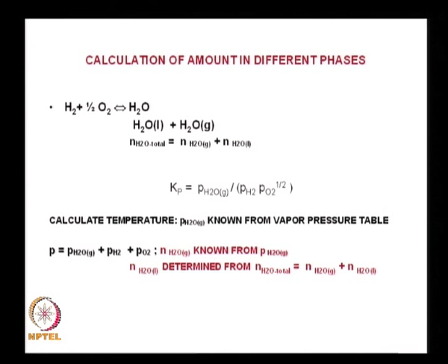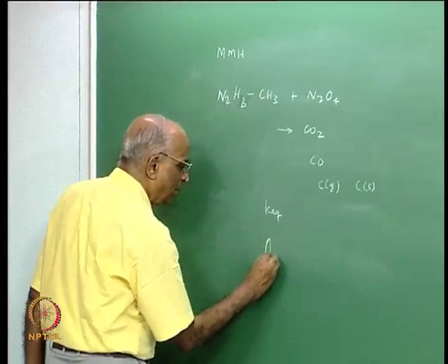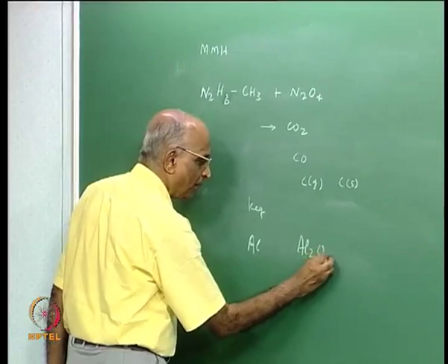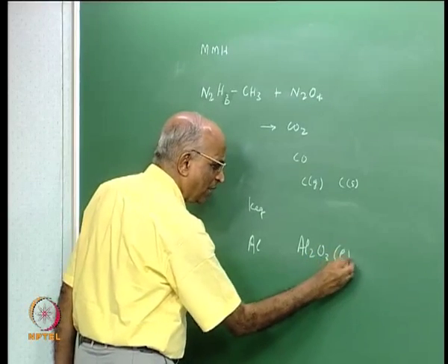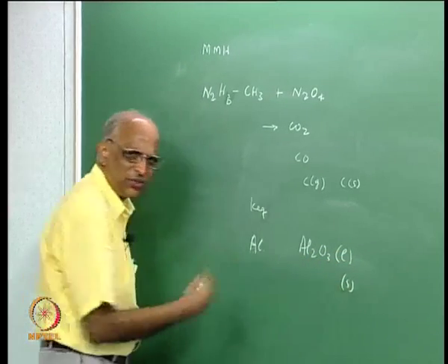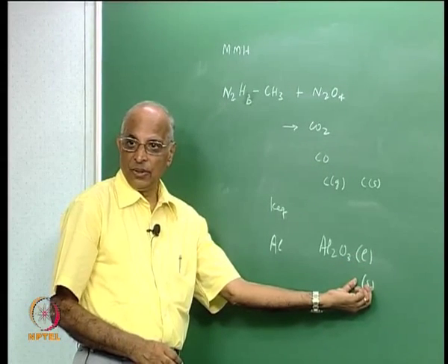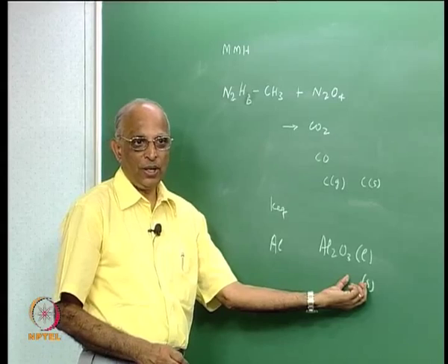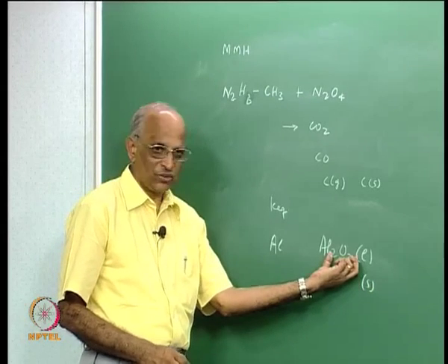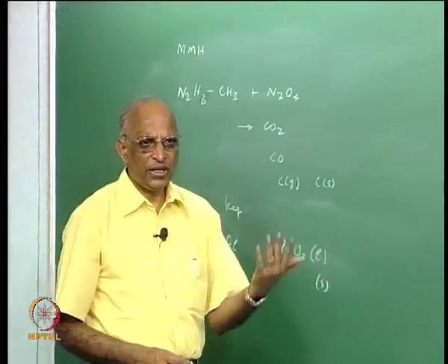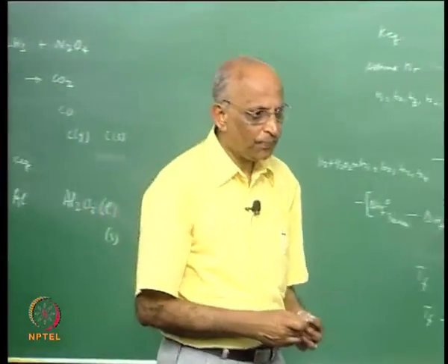And this happens especially when we have solid propellant rockets. I will consider solid propellants in the next class again. We add a lot of aluminium. Aluminium forms Al2O3, and this Al2O3 could be as a liquid phase, could be as a solid phase when it is coming out, and all these things have some energy in them. Therefore, we must be able to calculate, and those of you who do a project using solid propellants must be able to differentiate it, but the procedure is extremely simple.